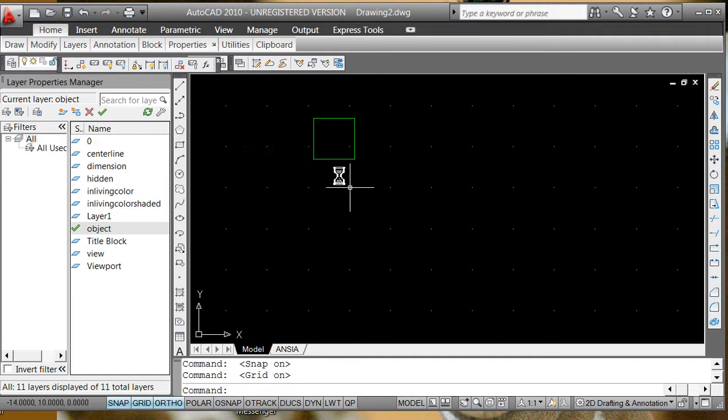Okay, that said, we're now going to review a real simple skill that we are going to grab pretty early, and that is that we're going to hit the F7 and the F9 together to turn the snap and the grid on and off. So off, on, off, on, off, on, off. We now would like to move. We could move the grid to our thing, but it makes a little more sense to move our thing to the grid because we're just getting started.